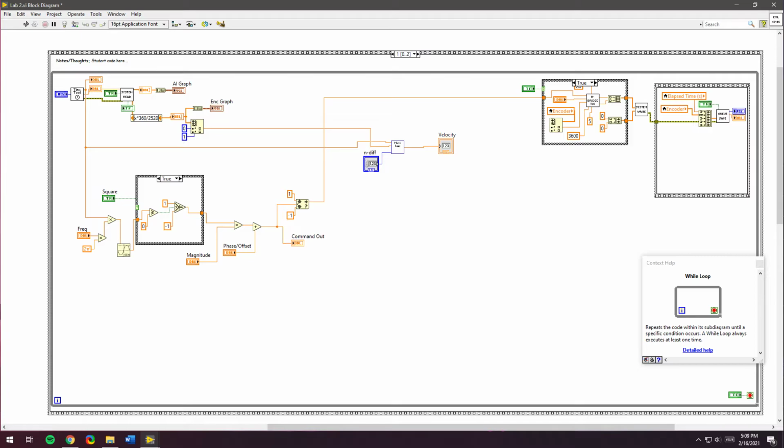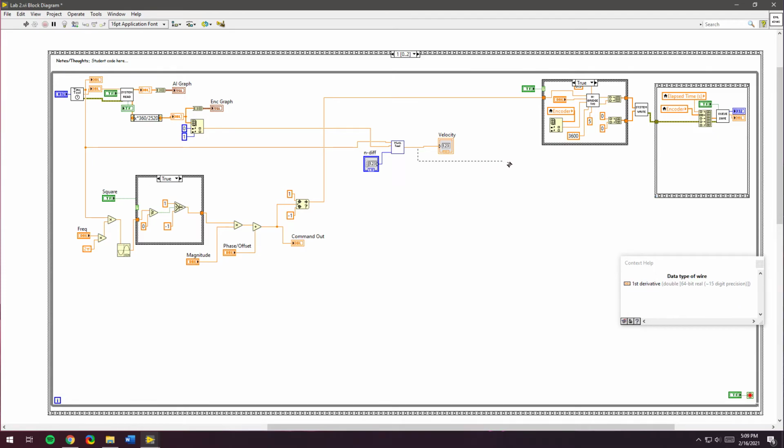We want to go ahead and get things set up to save. So we're going to put the motor's current rotation angle. We already have that here along with elapsed time, so we don't need to worry about those. Then the motor rotational velocity. I'm going to grab this wire, poke it through the side, and go on that top element. We want the frequency, so our frequency is over here.